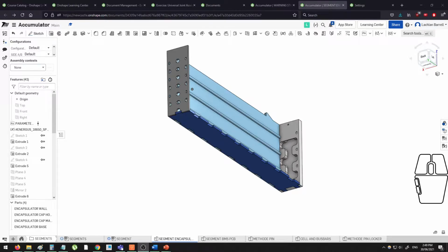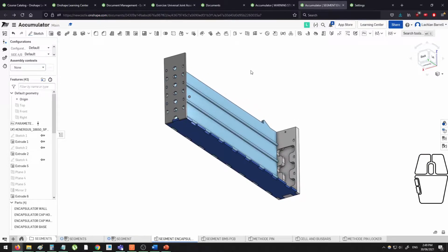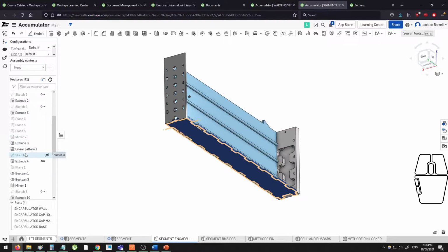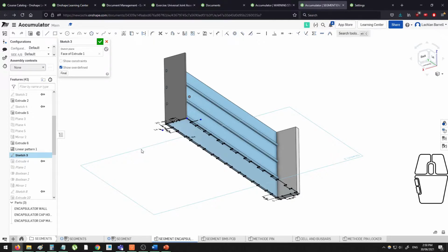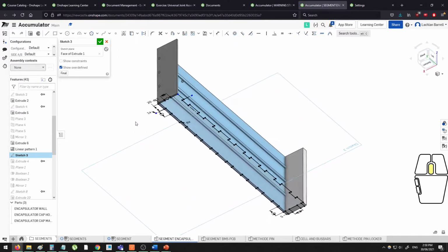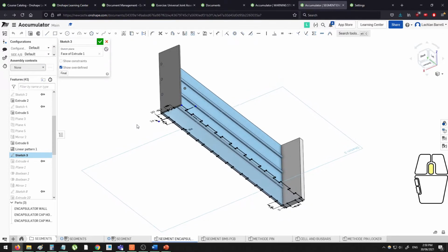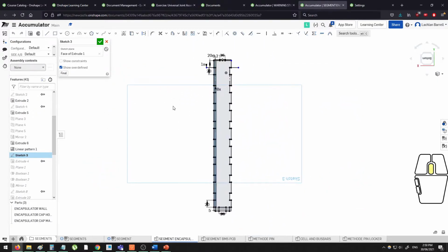Okay, so here we are in an actual part studio, and I'll rattle off some tips about sketching first of all. I'll start off with some general tips, and to do that I'll jump into one of our sketches here, so I'll double click it in the model tree. You'll notice that by default it doesn't snap to viewing normal to the sketch plane like our particular Creo configuration does. So to get around that, just press the N key to view normal to the current sketch.